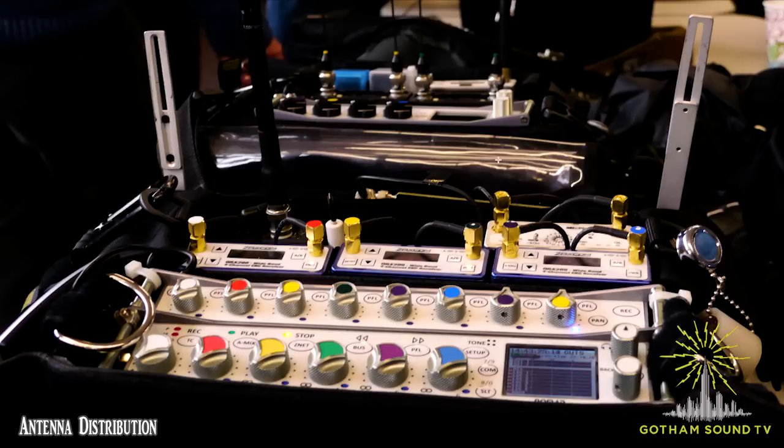If we look on the left and right-hand sides, you can see the SNA antennas feeding the splitter, and it's feeding those 3 receivers via RF distribution. Doing this will give you increased isolation, and just by doing this, you'll dramatically increase the range, depending on the environment.